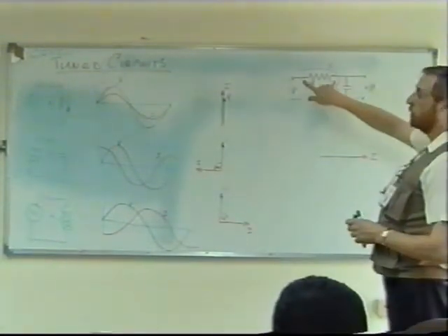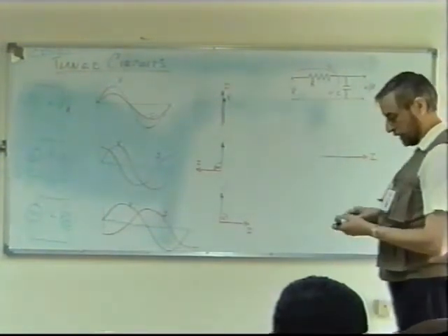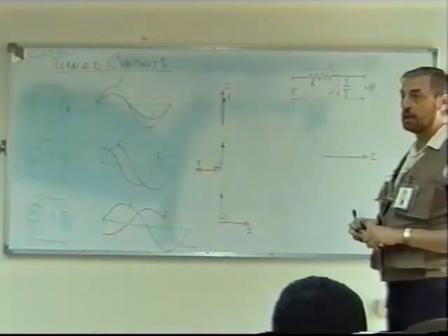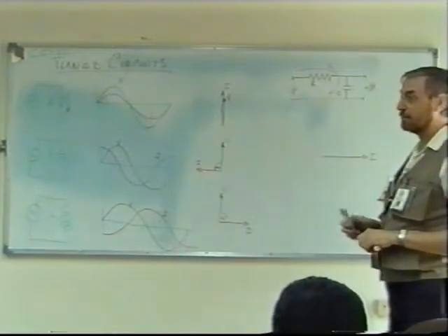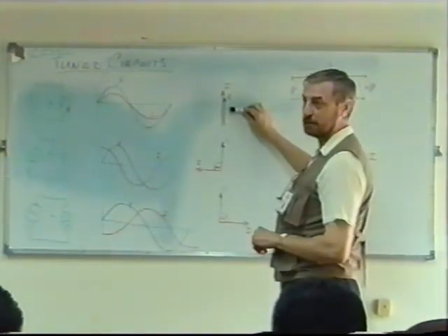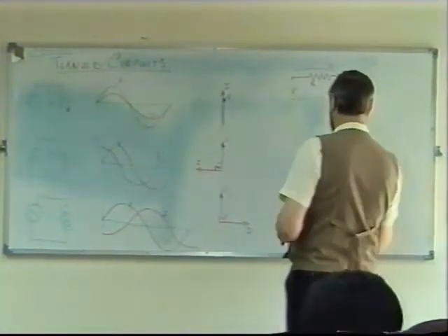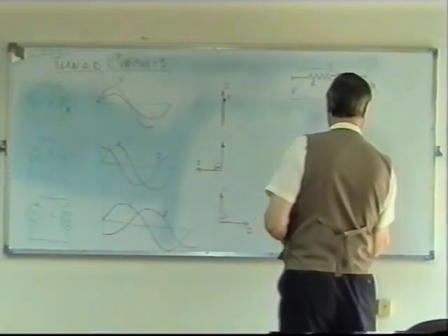If I was talking about the voltage across this resistor, whereabouts would it be in relation to this current? The voltage across the resistor. Yes, just the resistor for the moment. Okay, with the current. That's right. It's in phase with the current. Call that VR.